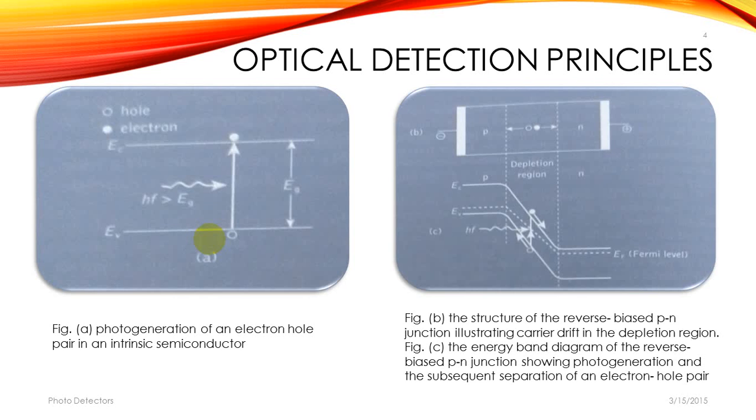The depletion region must be sufficiently thick to allow a large fraction of the incident light to be absorbed in order to achieve maximum carrier pair generation. However, since long carrier drift times in the depletion region restrict the speed of operation of the photodiode, it is necessary to limit its width. Thus, there is a trade-off between the number of photons absorbed and the speed of response.